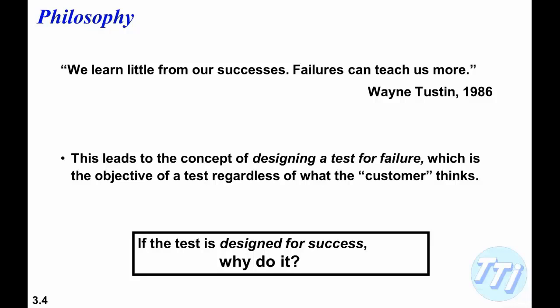But the whole point here is that we want to design our test for failure. That's got to be the objective of the test, regardless of what the customer thinks. If we don't design for failure, that means that we're never going to find a failure that might catch us in service. If the test is designed for success, why do it in the first place? It's going to pass no matter what.